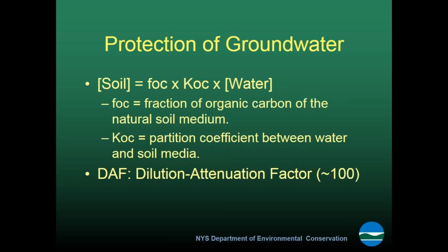The other thing is, as I was mentioning, the two elements of the dilution attenuation factor are the attenuation and then the dilution. So if you have a small area, discrete source of PFAS contamination, you actually might get some significant dilution taking place. But if you were to have a large area of air deposition, for instance, where you have square miles of relatively low-level soil contamination from an air discharge, you wouldn't have any dilution to speak of either.